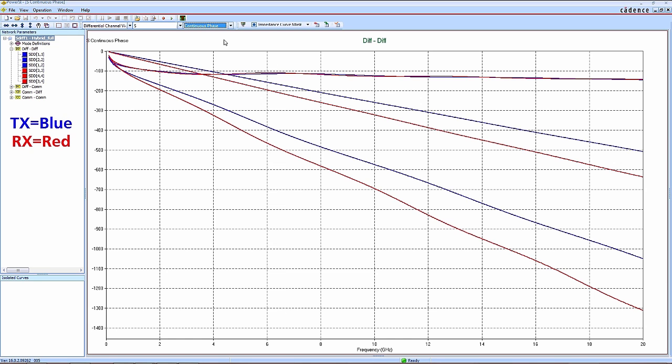longer. But before we go to the next step of local simulation for the cut design, let's consider what these results tell us already. The phase behaviors tell us the reflection occurs dominantly, if not entirely, at the board-side transition over the entire bandwidth. Since the board-side reflection phase starts at about -90 degrees and decreases slowly with frequency, we know this transition is highly capacitive and localized to the board-side transition.